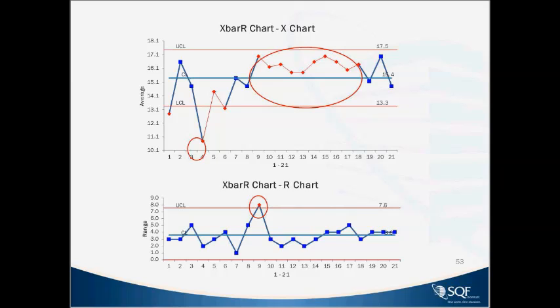But at least you know, and you've got a tool now, so that if something does change, and in the food industry with variation in materials and a whole bunch of other things, it's not uncommon to have special causes happening. But then you're going to react to it. So in these cases, you're reacting to the process. Nowhere on these control charts do you see specification limits. They should be a lot wider than them, and you want to be acting to the process, not necessarily to the product.